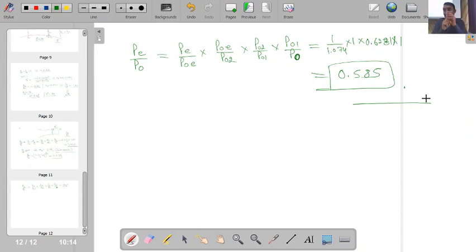Now in this problem, it is important to mention that it is given that the normal shock wave is occurring at A by AT equal to 2. But in reality, what challenge will you be facing? In reality, the challenge is that we will only know the upstream and the downstream pressure, but this data about where the shock wave is occurring will not be known to us. So the major problem is that we can apply this whole analysis, but before that, we must also be able to predict the location of the shock wave.